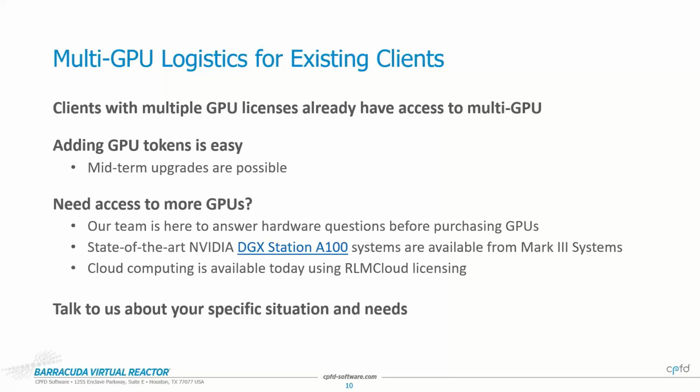One thing that we've had a few questions come up over, say, the past 6 months or since the release of 21.0 is people asking, how can you really run multiple GPU simulations? So we want to make sure that everyone knows a few things that are license related in terms of multi-GPU. The first requirement, as I mentioned earlier, is that multi-GPU is only supported on Linux systems, so keep that in mind. You do need to have access to a Linux system to do this.